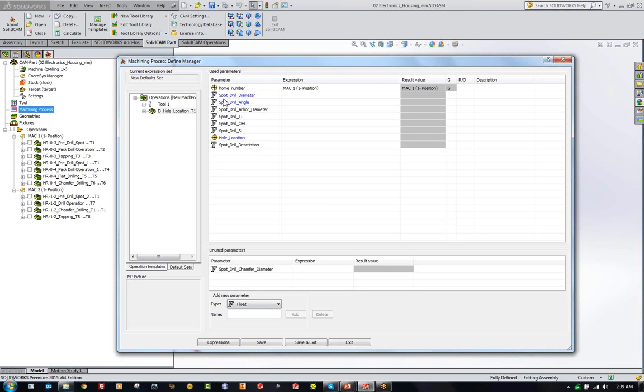In order to discover that, we have to get the information from SolidWorks out of the API. If it's a blind hole, that information is going to be in the HW_hole_diameter. If it's a through hole, the value for that is going to be in the HW_through_diameter. So it's two different variables.